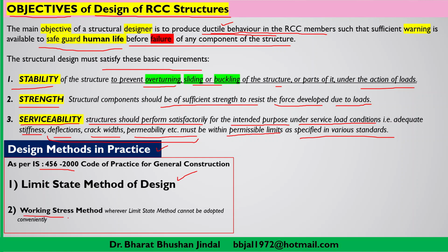Secondly, you can also use the earlier method of design, that is the working stress method, but the code says that wherever the limit state method cannot be adopted conveniently, you can use the working stress method. Otherwise, these days, we have to adopt the limit state method of design. In later lectures, we will understand the difference between the working stress method and the limit state method, and which one is better and why.